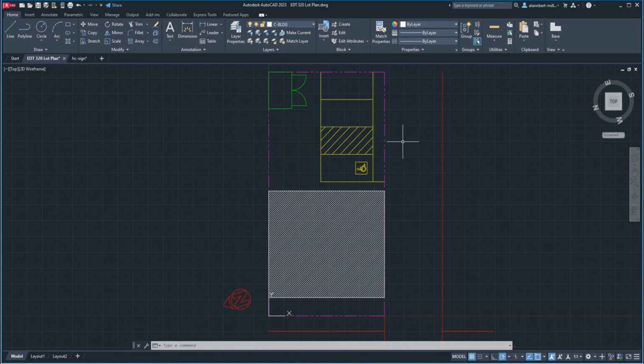And then the last thing that I wanted to do is maybe signify where the 15 foot setback is. So I'm going to do an offset, enter 15 feet, 15 apostrophe, click this back, and over here. And then I just want this to be the same property, so I don't need to put it in a different layer. I can leave it as a property line. So when I click on this one, this is under C prop, which is a property line, but I don't want it to be thick like a magenta. So I can actually just change the color directly.